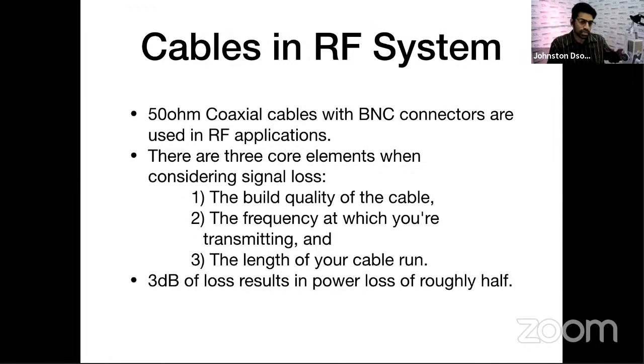Like for example, if your transmitter and your IEM antenna is about 2-3 feet apart, fine, you can use that cable. Do not use unnecessarily long cables as well, because the more cable length you have, the more signal drop there is. Okay, basically every 3 dB loss is roughly half the actual power that you get in the transmission. So don't unnecessarily use large cable runs. Don't unnecessarily use line amplifiers, because the moment you amplify any signal, you're also raising the noise floor up. Okay, so your cable management needs to be very smart and precise.